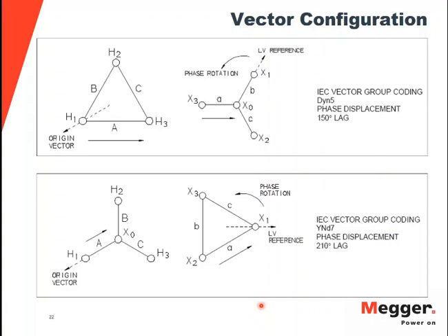That's a good question. Usually when we talk about voltage dependency, it also has a lot to do with the design of the transformer. That 20% or below that I mentioned is what we have observed when we test a number of different transformers out in the field at different OEMs, all that kind of thing. So one thing I want to mention is that voltage dependency does not mean that there is a problem with the transformer. All it means is that you need to use an appropriate amount of voltage to get good readings.